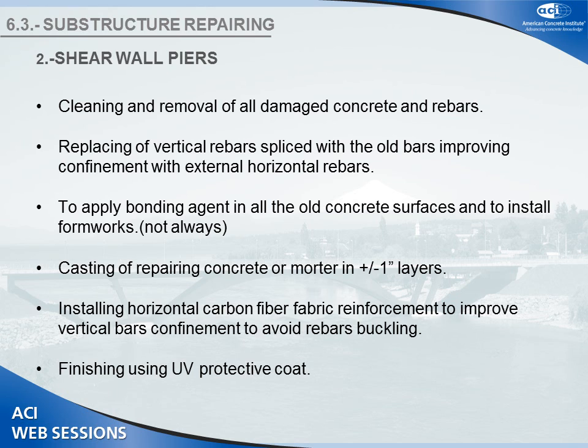Finally, we cast repairing concrete or mortar, depending on the case. We also use a horizontal wrapping with carbon fiber to improve the vertical bars' confinement and also shear, in order to avoid rebar buckling. Finishing, like in the other cases, using a UV protective coat.